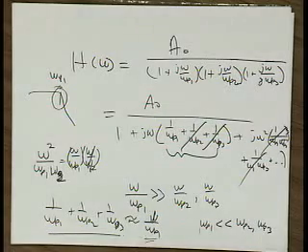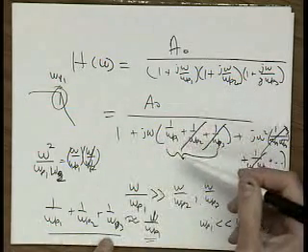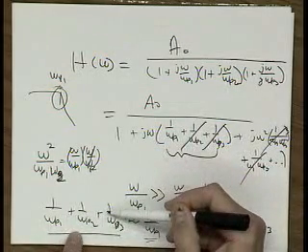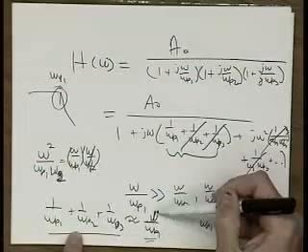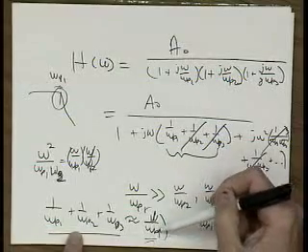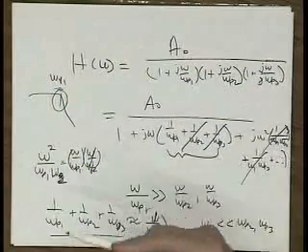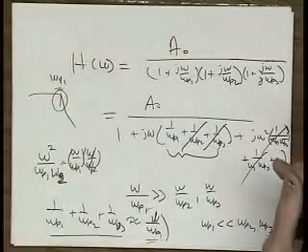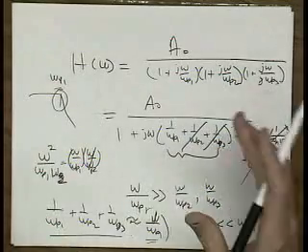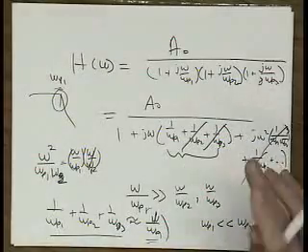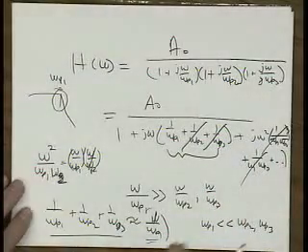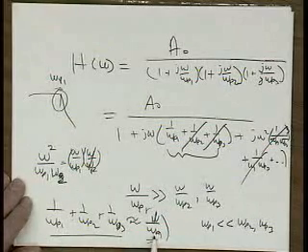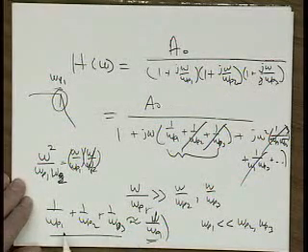So this is a somewhat crude argument for why, if you take the inverse of all the pole frequencies and sum them, you end up with a good approximation to the dominant, lowest frequency pole. There's actually a much more sophisticated way to come up with the same result, and I think Gray and Meyer has it in there. I don't know if Razavi does as well. There's some circuit theory way to get the same answer. The question is, how do we get this approximation to the sum of poles? That's what zero value time constant analysis is.